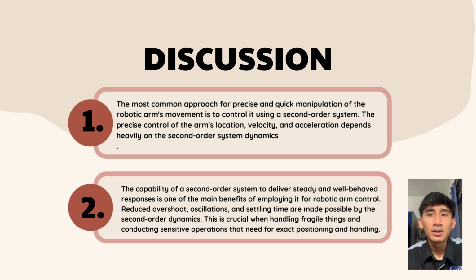We drew a block diagram and established the transfer function. The system's peak time, settling time, and percentage overshoot were all calculated. However, we discovered variations between the outcomes of our manual calculations and the result produced by MATLAB. The transfer function of the system was also transformed into a state space representation using MATLAB. This demonstrates that the outcome is solely determined by the system's state variables.